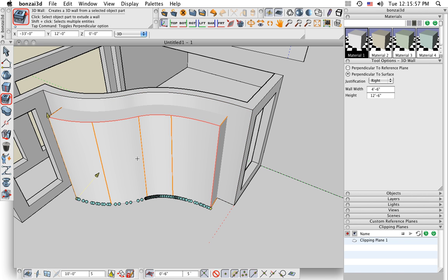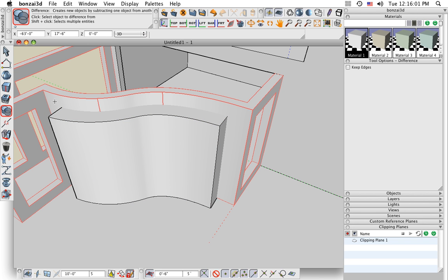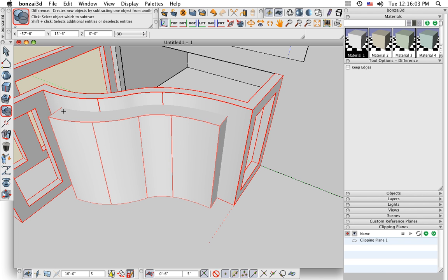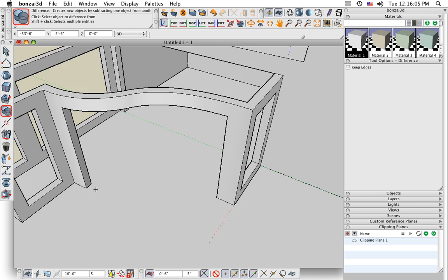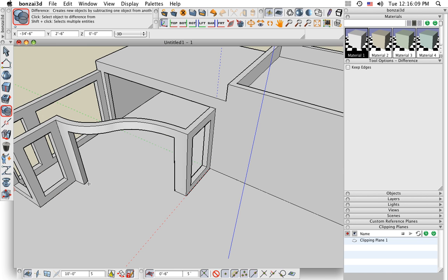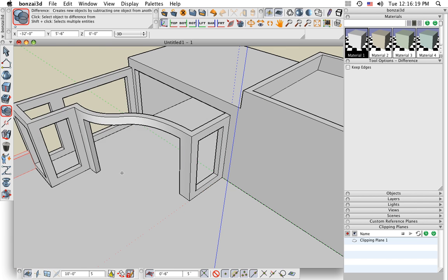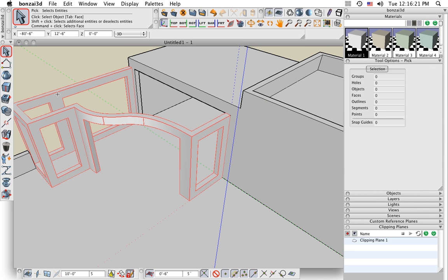And the reason why I did it this way is now I can use the difference Boolean operation to subtract one shape from the other, and I have a perfect right angle wall opening in here. So I could have just stuck a cube through this too, but then the wall here would not have a right angle. Okay, let's put a roof on that too.